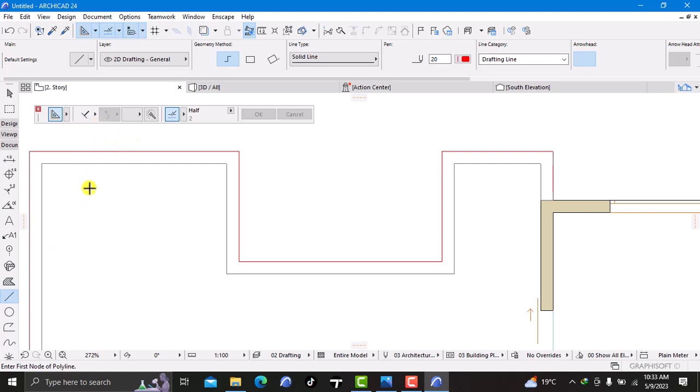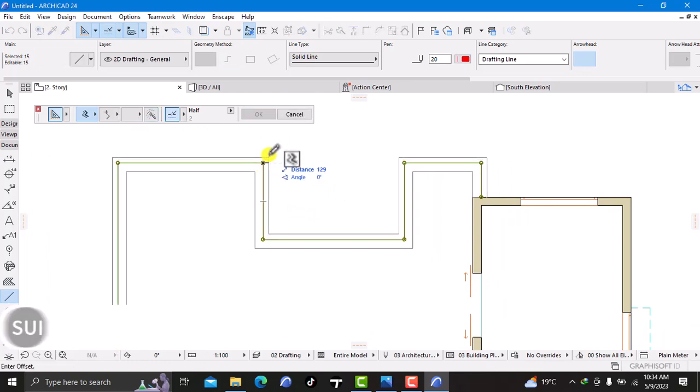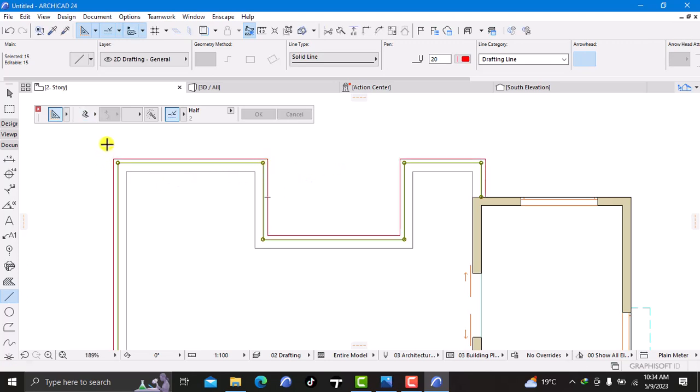offset this. So in order to offset this, I'll go back to the relative construction methods, click on this and use the offset. Next thing that I'll do, I'll just select my line, right over there. Just basically use the magic wand, select this line and offset it at a distance of 100. I don't want it to be very big, so I can do it at a distance of 100. Enter, and I still need to offset it again.